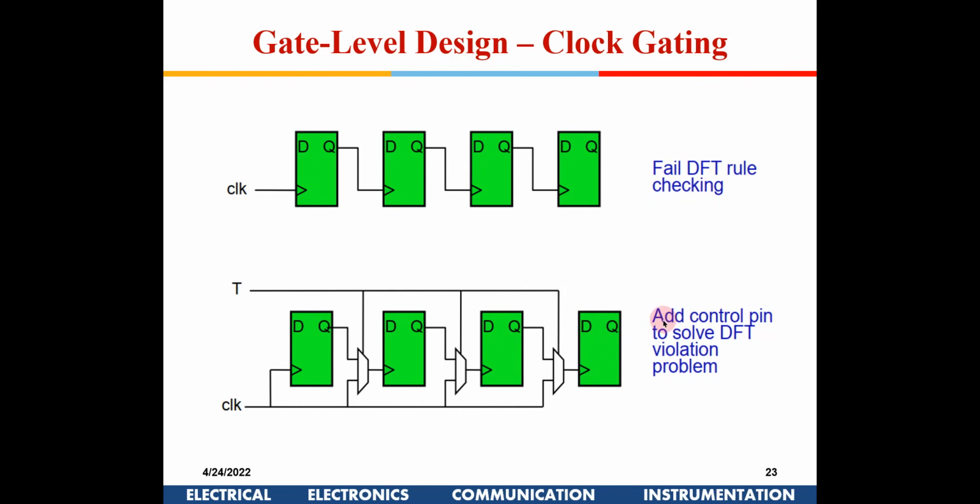So basically, two takeaways from this slide. One is that asynchronous clocking is low power, but however it is not suitable for DFT. DFT stands for design for testing. In that case, we can put an additional mux here, and for normal routine working, we can have asynchronous clocking of flip-flops, and for testing, through this mux we can remove this asynchronous clocking and put the clock to these circuits.